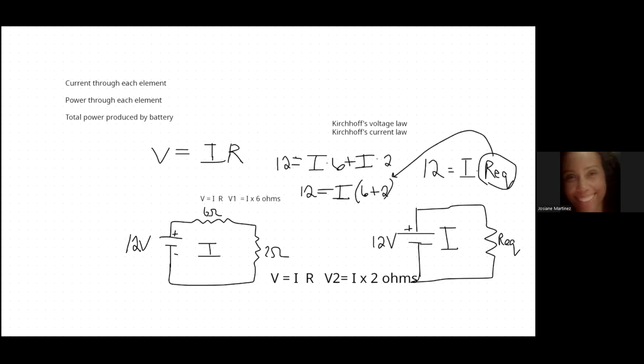Very straightforward. We could understand it using the physics explanation of resistivity and length and all that. But if we didn't have the same material, we could still prove this has to be true. You just add the ohms of each series element. Now you have the two principles you need for simplifying any resistor circuit.